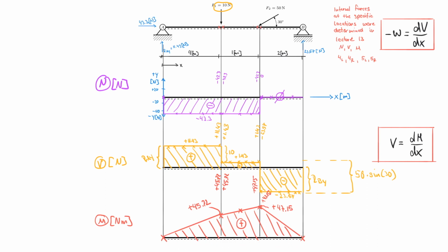And of course, an engineer would never say that it's actually smiling. An engineer would say it's bending downwards. And therefore, you have tension on the bottom and compression on the top. I say that again. So if the beam bends downwards or deflects downward, then you have tension in the reference fiber or on the bottom and compression on the top.